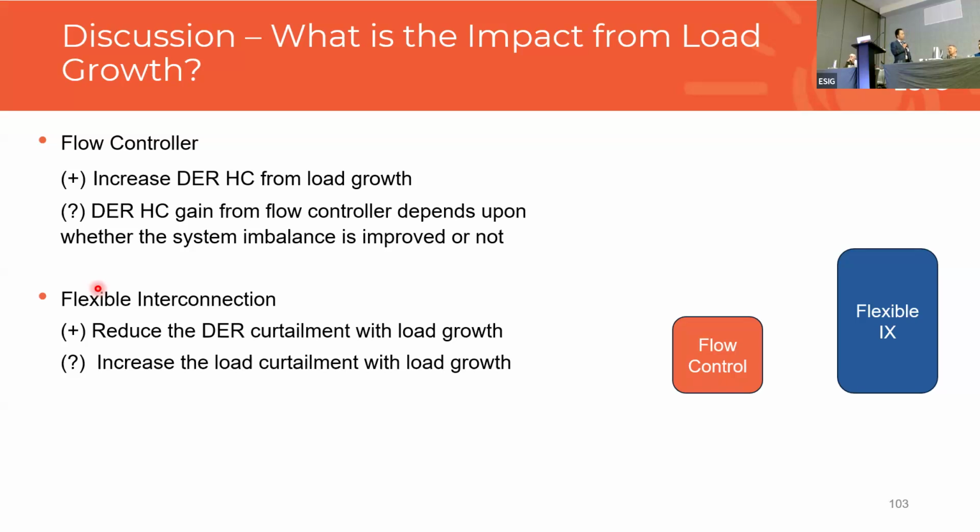And the second part was increased load curtailment with increased load growth. Yeah, that probably is accurate too, with the caveat of what type of load it is and what the load profile looks like over a period of time. So that depends on the load shape. Correct.